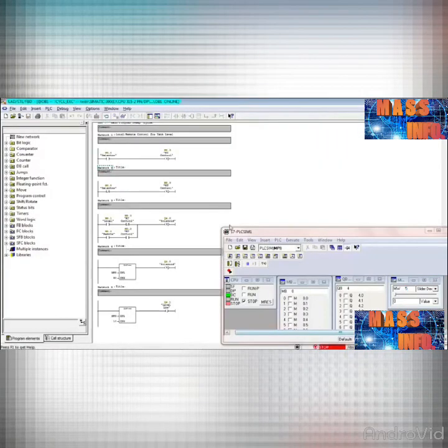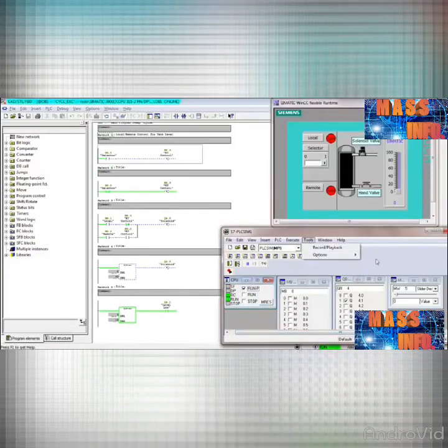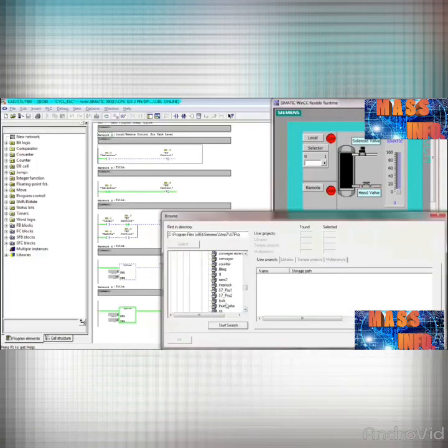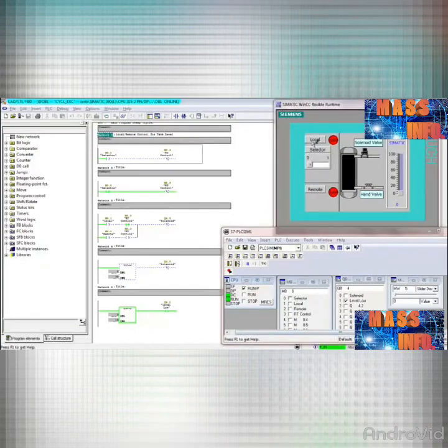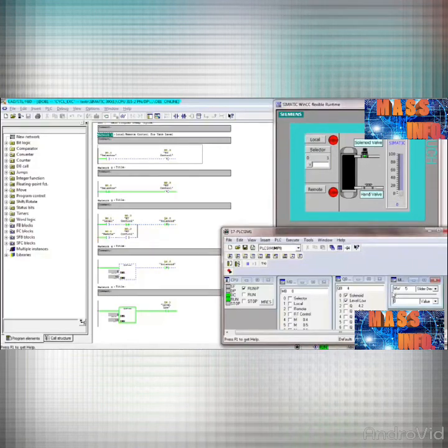Now download the program to the PLC simulator and attach the symbols with tags. So now you can visualize how control and monitoring happen. I can control objects from the HMI or simulator to demonstrate that it's working, and I can change the value of a button or slider from both the HMI and the simulator.